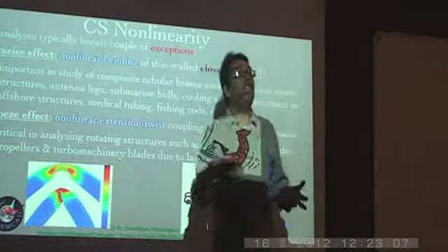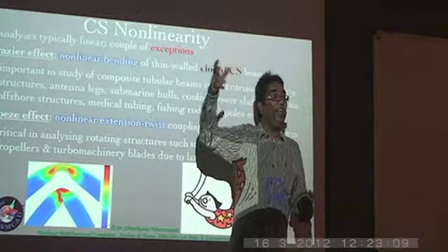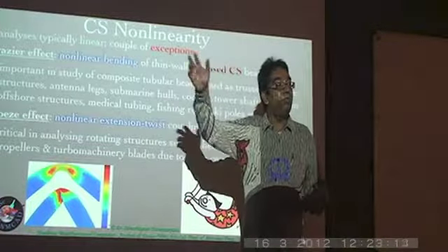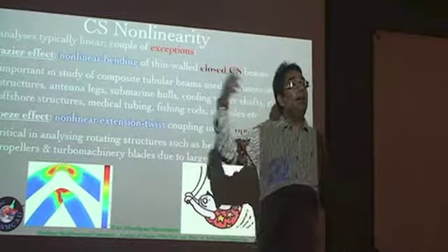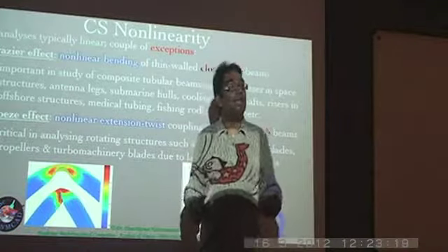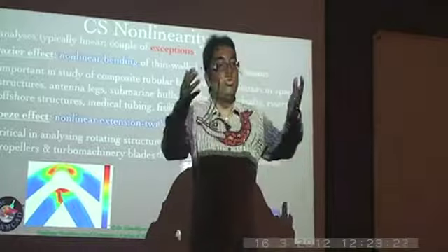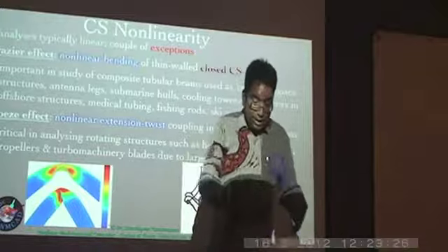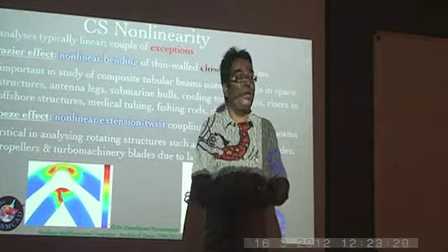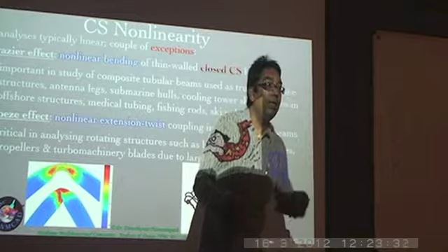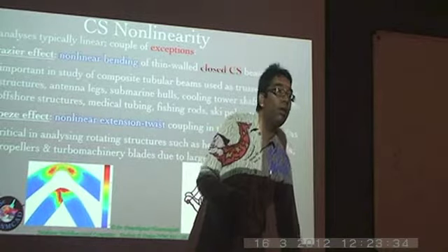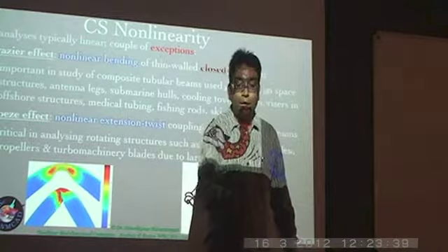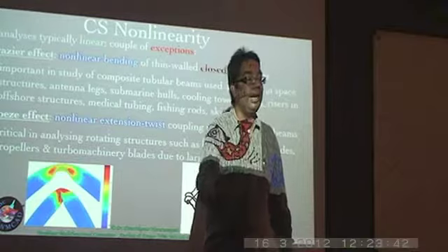Almost all of the control of a helicopter happens through the change of the twist of these blades. Of course, there is an initial twist in most of today's rotor blade designs, but in addition, the way the pilot operates the helicopter, whether he wants to move forward or rearward, sideways or upwards, he basically has two pitch sticks that he controls. One is called the collective pitch stick, which is either lifted up or brought down, and then there is a cyclic pitch stick which can be moved left, right, front, back, or combinations of these in any direction.